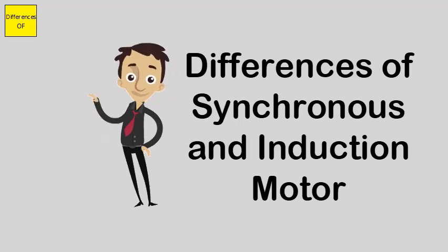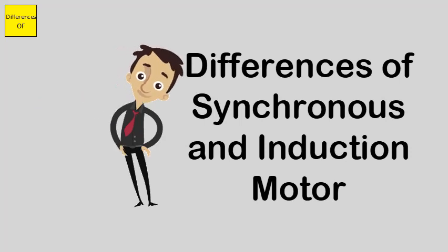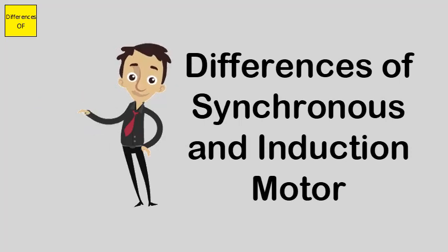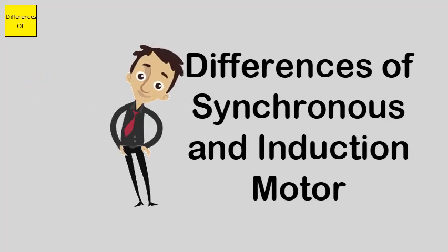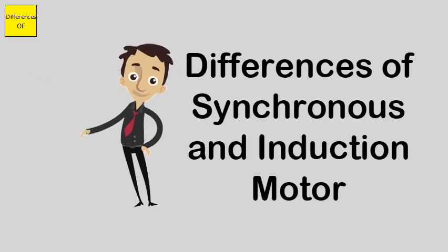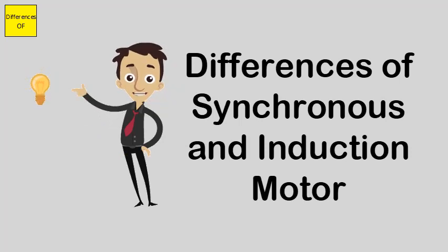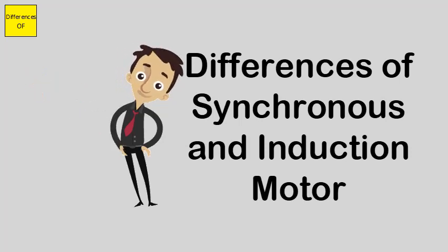The power factor of a synchronous motor can be adjusted to be lagging, unity or leading. Induction motors must always operate with a lagging power factor. Synchronous motors are generally more efficient than induction motors. Induction motors are generally less efficient than synchronous motors.